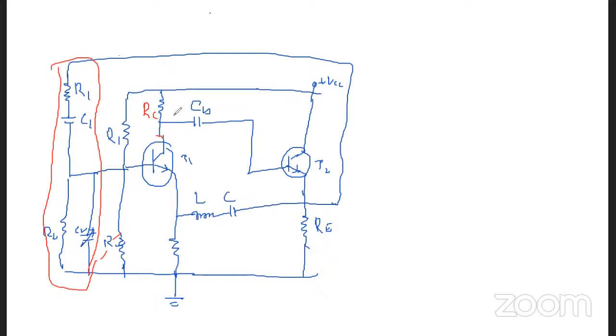But it simultaneously suffers a phase shift of 180 degrees in this case. A further 180 degrees of phase shift is introduced by the second transistor. So a total of 360 degrees, or zero phase shift, will be there. Hence the feedback will be positive and the circuit becomes self-oscillatory. The RC element of the Wien bridge provides a negative feedback which prevents oscillations at all frequencies. So the oscillator becomes sensitive to a signal of only one particular frequency. So the Wien bridge oscillator has good frequency stability.